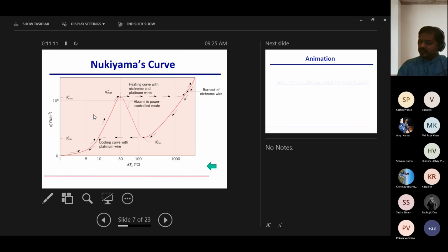What you see here is the boiling curve. But what was he doing? He was increasing Q, the heat flux at the surface. And so initially he saw, yes, there is something called natural convection. Then he saw pool boiling, etcetera. That heat flux going up, up, up. And suddenly, when he came to this part, right, which is the critical heat flux, okay, the wire snapped.